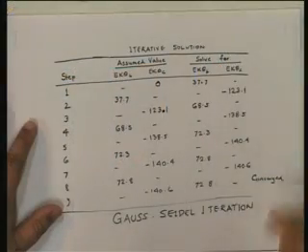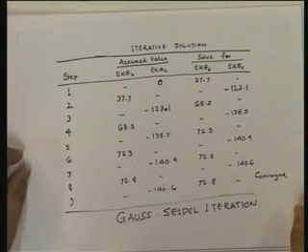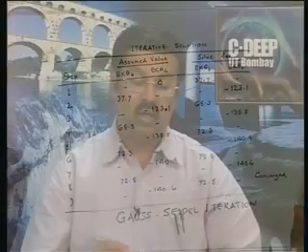Okay, so let us go back and look at what this implies. Of course, once you've got this, you can plug in these values into MAB, MBA, etc. and get it. However, moment distribution is not the Gauss-Seidel iteration procedure. Let us look at what this implies in terms of the moments themselves. Note that we evaluate Ek theta B, Ek theta C not because we want to find the value of theta B and theta C. Understand that very rarely are we interested in what the rotations are. We are interested in calculating the rotations so that we can calculate the moments. So now let us see what these moments actually look like.